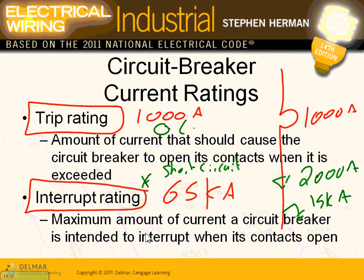So if they have the trip rating, how do we size conductors? Anybody can tell me how you size conductors? We size conductors based on this. Very important. Do we size conductors based on 65 kilo amp? Not really. Well, no. At this point, no. So that's your trip rating.